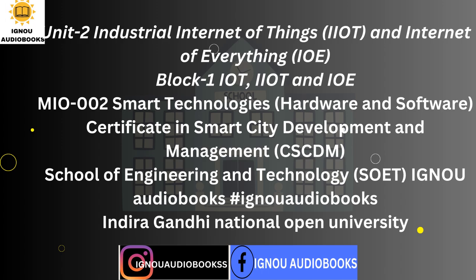IoT is about digitally networking things such as sensors and actuators from the very first meter and then securely all the way across the internet so all their data can be accessed from anywhere including the other side of the world. For the industry this means 4 to 20 milliamperes and on-off signals are no longer sufficient. You need digital networking all the way from the sensors and actuators, bus or wireless. It is when it comes to the sensor.